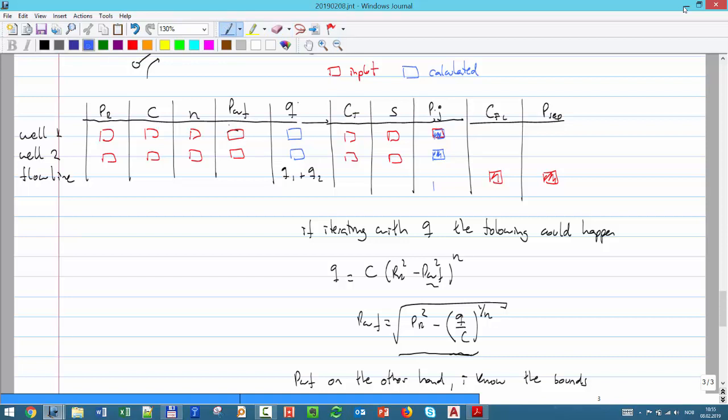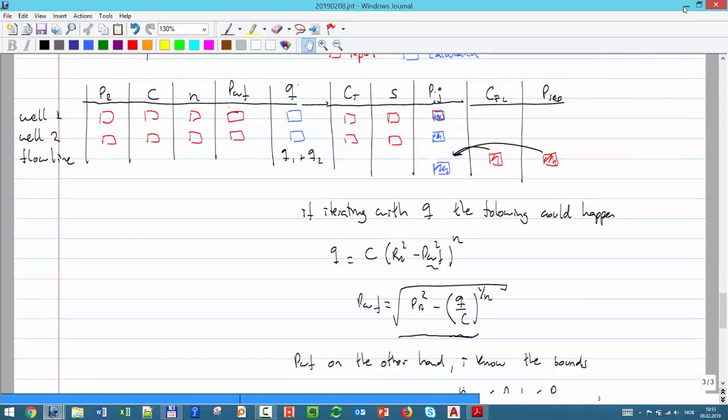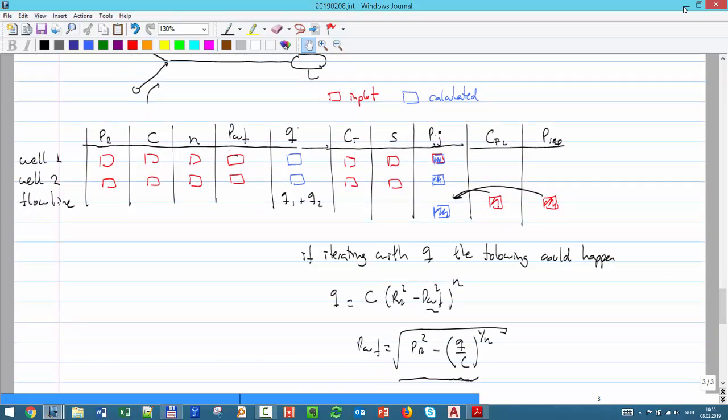Okay. So you can actually use these two to compute. One of them you go co-current, you go with the flow from reservoir, bottom hole, and junction, and the other one you have this rate, and then you go backwards to find that number. If you're going to have a solution, what should happen here?